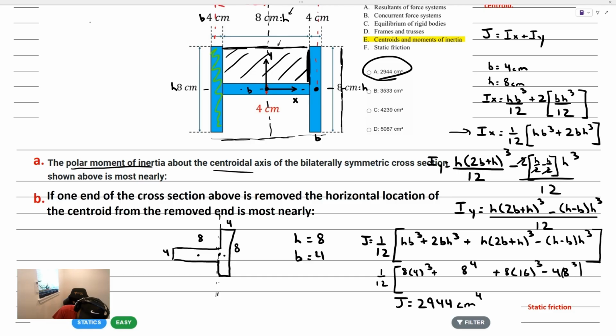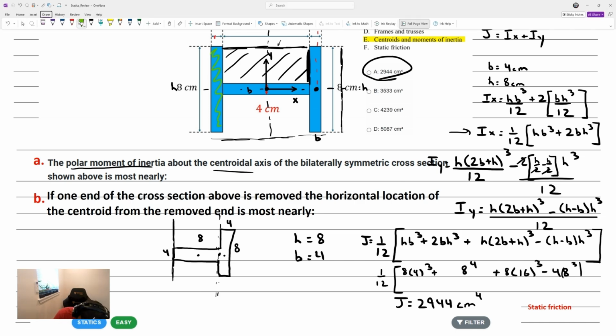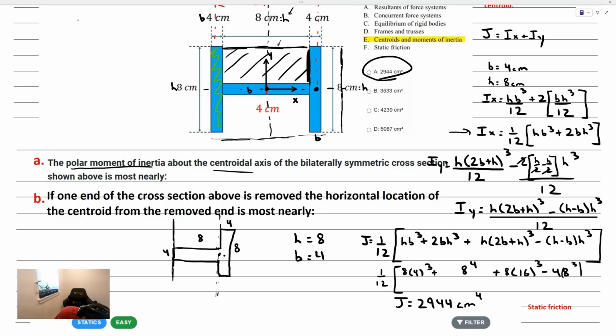Okay, so fundamentally, I usually picture an axis here, hanging off the side of a table. What I'm doing when I'm taking the centroid is taking a moment of this area, placing the centroid right there, and a moment of this area, and saying that that must be equal to the total area placed at a special distance away. Area 1, x bar 1, that's this moment right here, plus area 2, x bar 2.